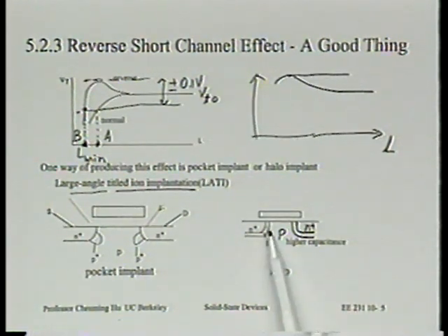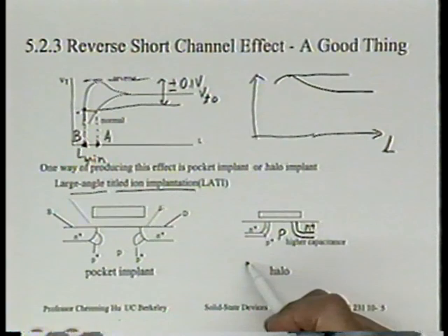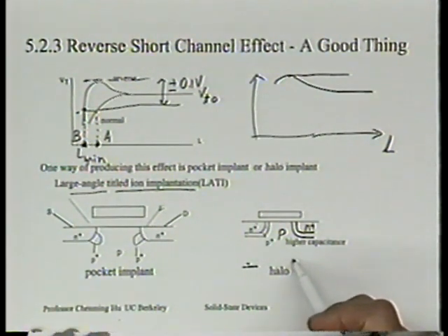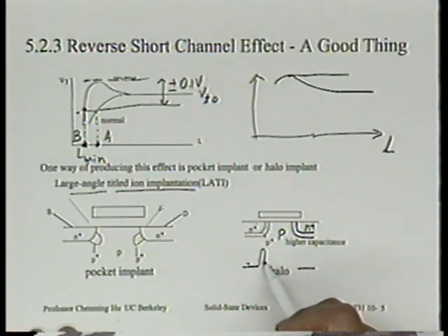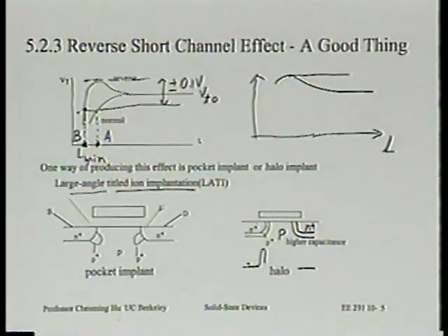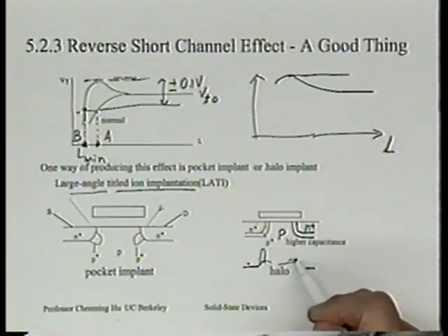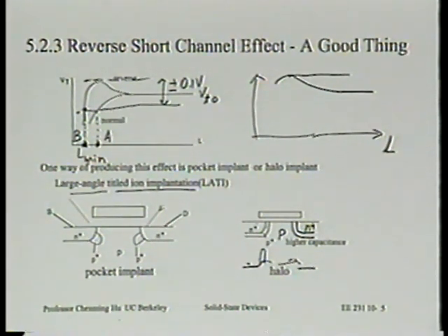Can we really visualize this transistor as 3 transistors in series? I know it's tempting, but I'm trying to preempt that question. This is not a good picture to look at. Instead, you should think about extending the last lecture to draw the energy band diagram from the N plus source through the P plus, through the P, through another P plus, back into the N plus. If this P plus region is very narrow, will it go to where a uniform P plus would take you? It would not. In other words, this P plus and P all have impact on each other. You see what I'm saying? You cannot just visualize this as 2 transistors in series.